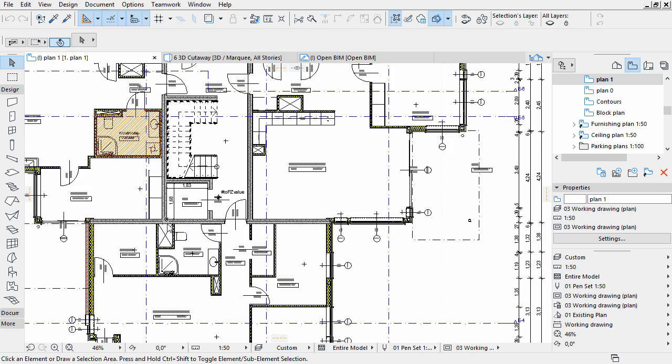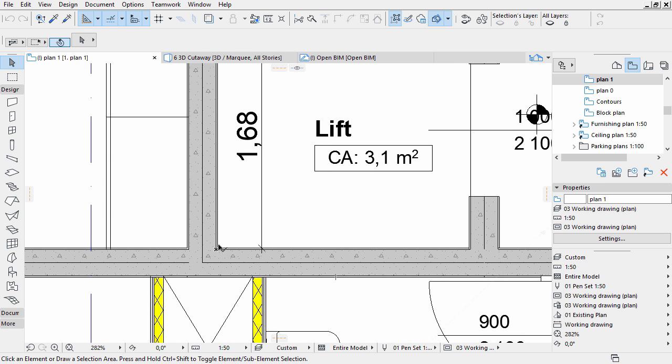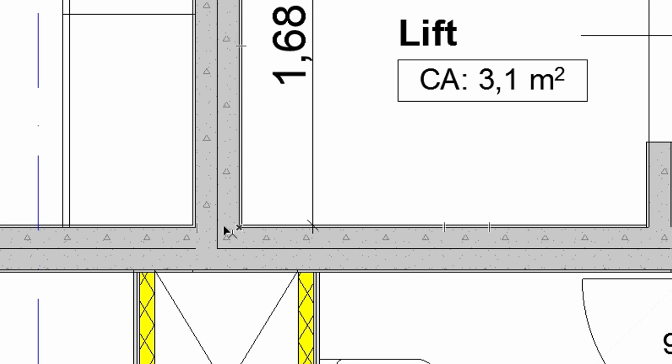Define a typical point of the building as the project origin. In the future, share this point with the disciplines working in other softwares. During the design process, they should take care to place elements with respect to this project origin. For instance, this point can be a wall floor joint, so we just have to define the offset of the floor, marking the joint.